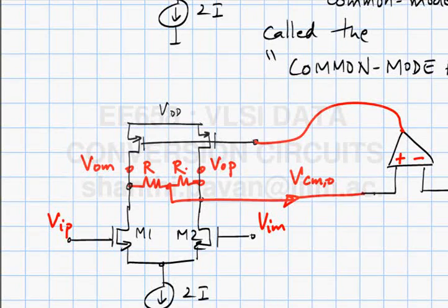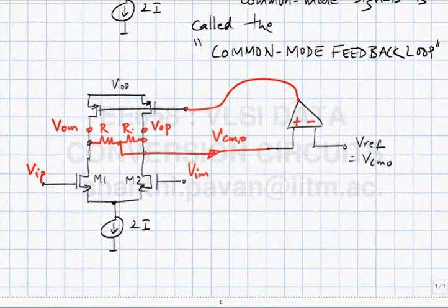So what is the problem with using two resistors? Adding two resistors to find the average of the output is a perfectly normal thing to do as far as the common mode loop is concerned, right? But in our whole endeavor to measure the output common mode, we shouldn't screw up the differential mode. After all, we are trying to realize an amplifier with a large differential gain. So what is the differential mode gain? Assume all the transistors have infinite output impedance. It's simply Gm times R.